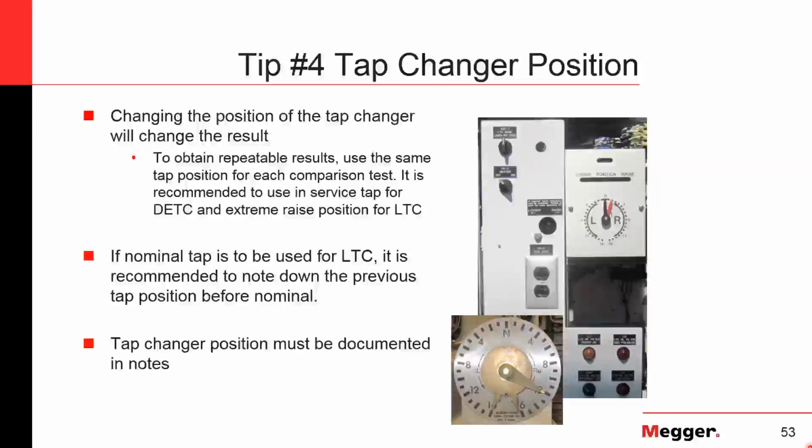So if you did your test and you have some results on your SFRA, and something makes it different, take that information. Do the analysis with the analyzer that you have on the software, talk to the MEGGER guys, give us a call, or you can also do a validation in the field. Take your piece of equipment, do your short circuit impedance test and get the results. Then you will see that you have more information to bring to the table and discuss, based on the limitations that we have for each specific test.